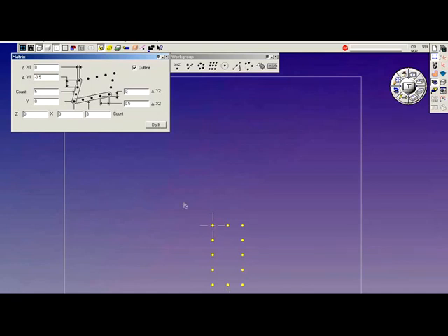Okay, so that's the matrix dialog, and I'm sure you all know that we can do math in all the windows. For example, if we wanted to do a trig function, sine, cosine, and tangent are generated by using the letters S, C, and T. If I type in the number 45 and the letter S, it gives me the sine of 45 degrees.